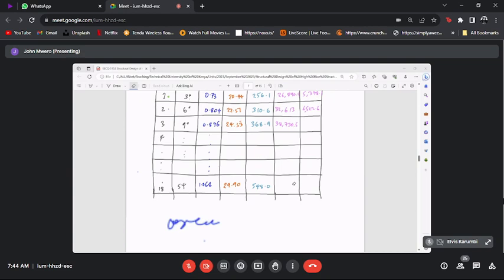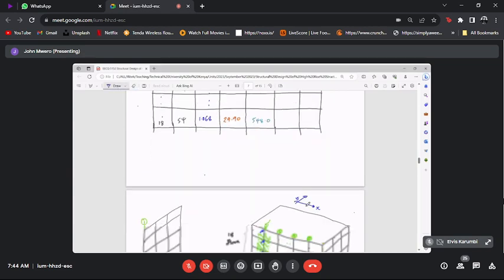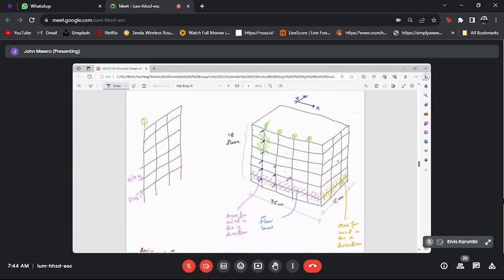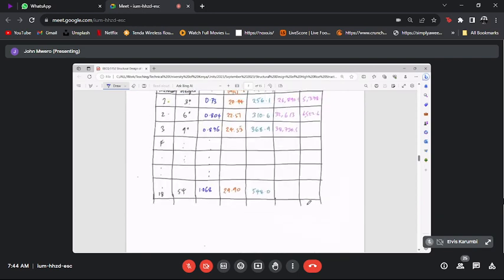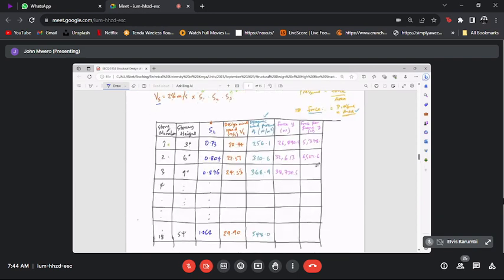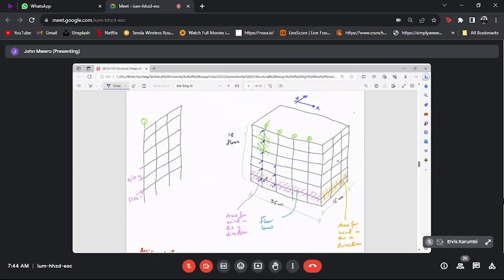If you will just remember, on the whole building, on one face, the longer face, which is 35 meters, we calculated that. We went ahead to, again, divide that force per frame, so that we would have the values that we would put in at the nodes of this frame as point loads courtesy of the wind.